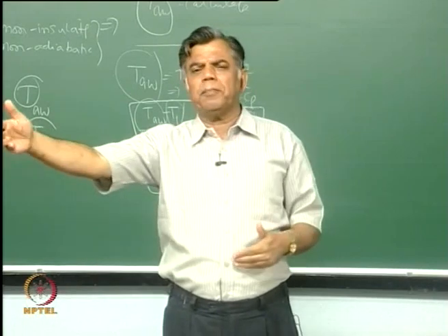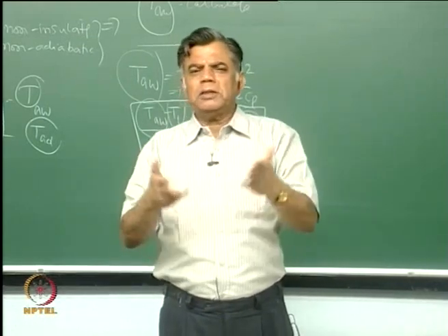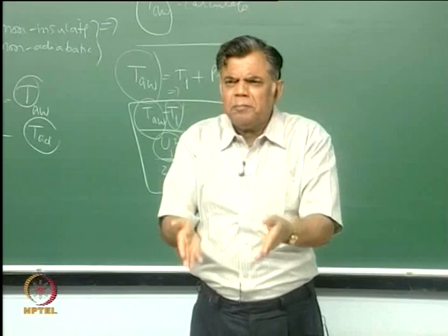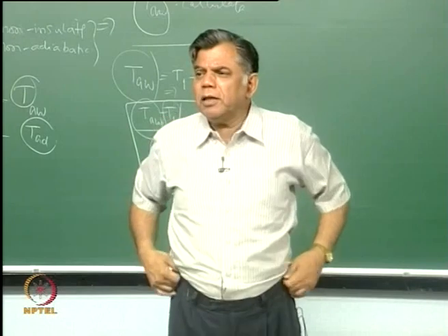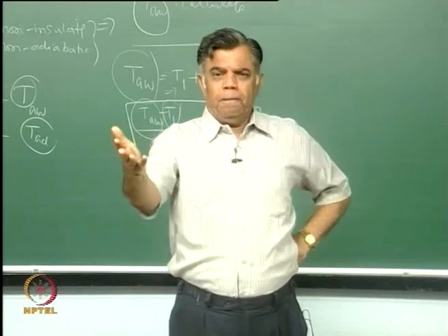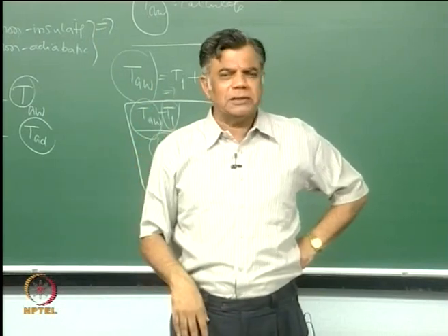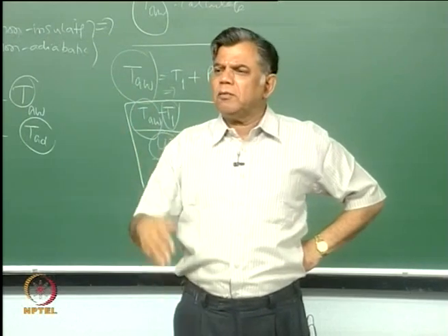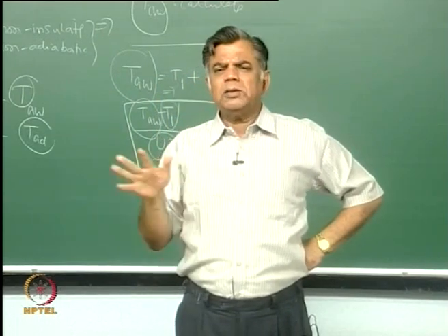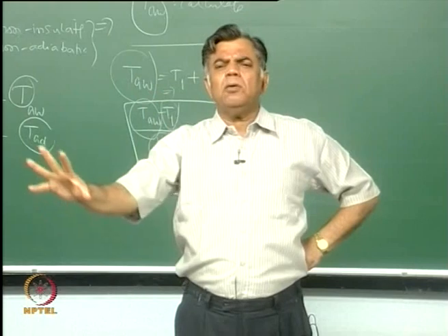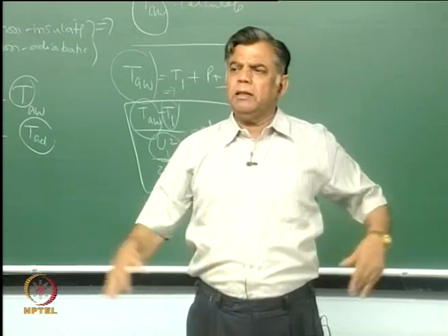So in a boundary layer flow it can be Prandtl equations, but in this case there is no name given to those 4 equations, d square u by dy square, there is no name, but you please look at them. It is like in conduction, what is the simplest expression for conduction? d square T by dy square equal to 0. You can't get anything simpler than that with two boundary conditions. Similarly, you have here d square u by dy square equal to 0. Y momentum has taken care, energy equation, we wrote everything. We said there is no heat generation, but we did not say there is no viscous dissipation, purposely, because we wanted to study it since it has du by dy.